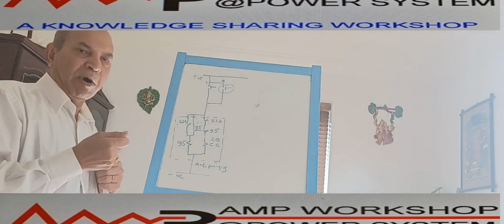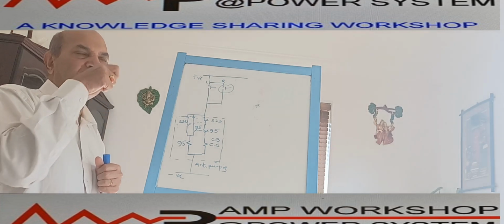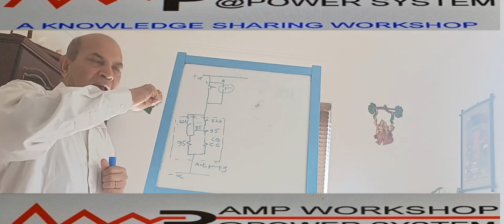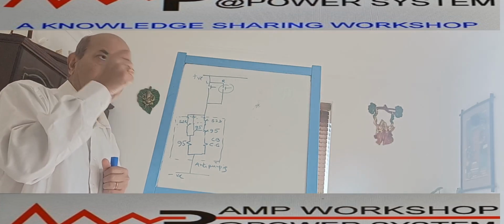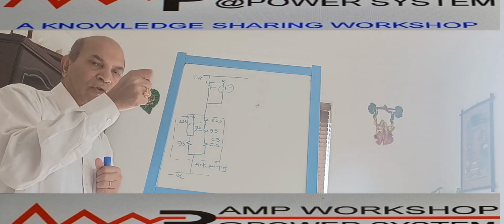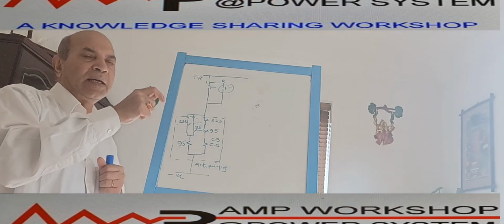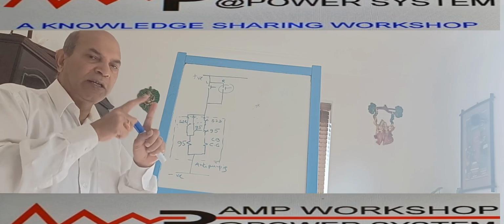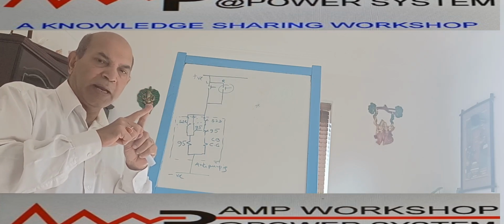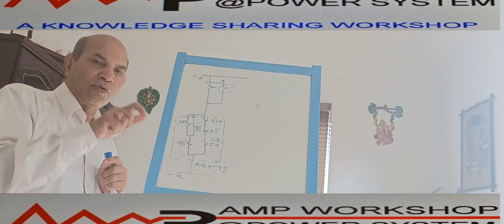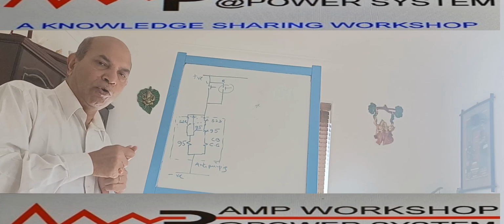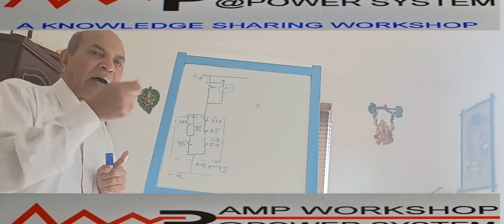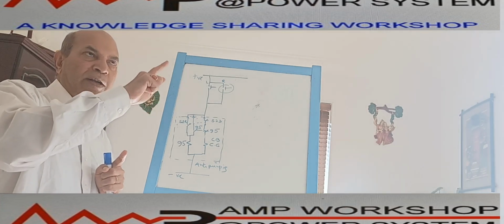But if you are more smart, you may think, okay, I may miss that 12 point, so let me hold the switch in advance and keep it held, so that when it comes to the 12 position, it will be closed immediately. That is not the right way. It can happen that at 12 o'clock, when the hand is on the 12 o'clock on the synchroscope, it is in synchronization, but it is not actually so. The two vectors are continuously rotating. At that moment the two vectors are in line, but again they shift immediately. So if you maintain the closing command that way, if you hold the switch continuously, then what will happen? It will close, and then it is closed on a system that is actually not synchronized, but the pointer is passing through the 12.